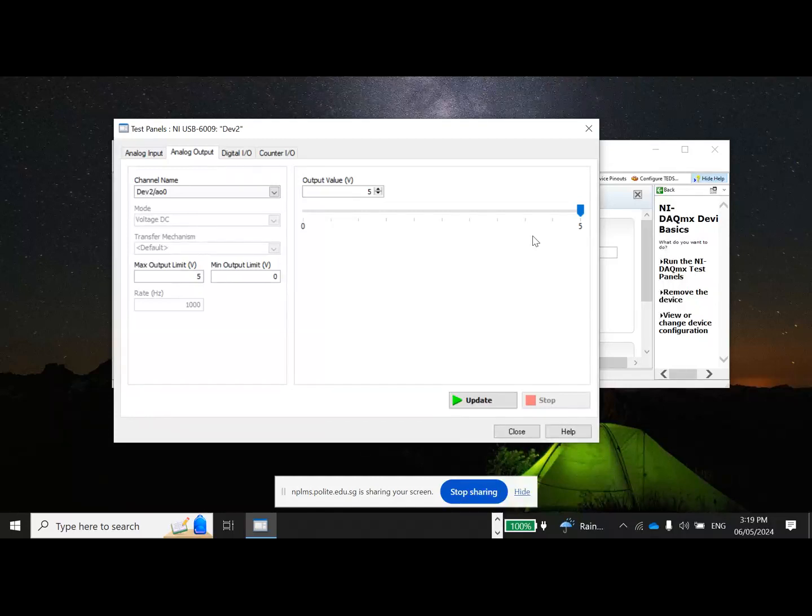Anybody cannot switch on the lamp? I don't know whether it's me or the hardware. Are you able to? I cannot turn on the lamp. Mr. Teo, maybe help. Sometimes the bulb is not tightened properly. Need to twist a bit, then the thing sits properly. Sometimes it's a contact problem. But mostly, on this table on my left-hand side, I can see the lamp. That means you're all following the procedure properly. Okay, good, I can see all the lamps light up.